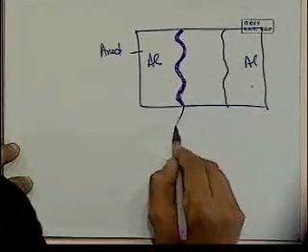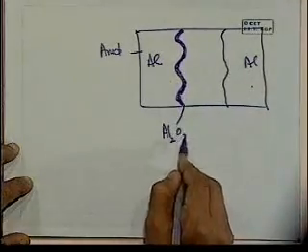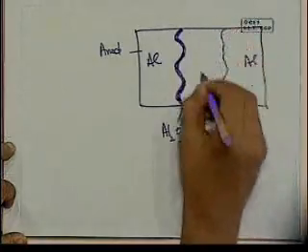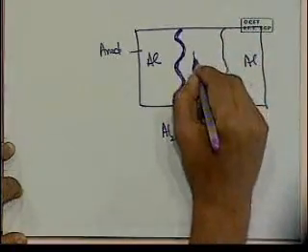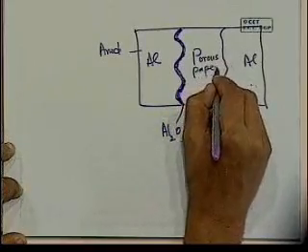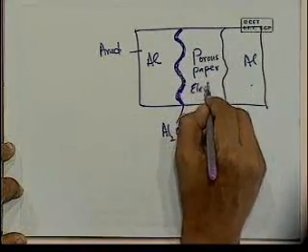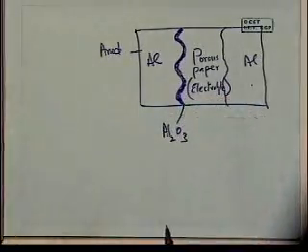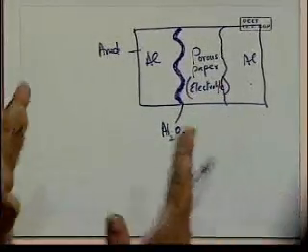But on this foil, we have the formation anodically of an oxide. Both these foils had been etched, so that increases the area. And what we have here is the porous paper filled with the electrolyte. This is what it will look like in cross section.